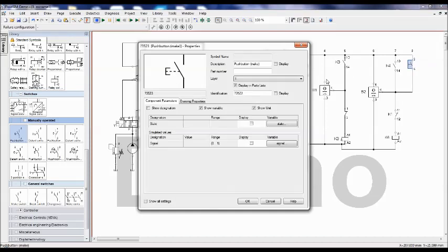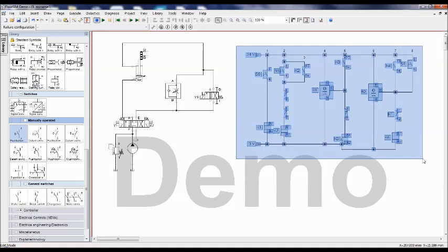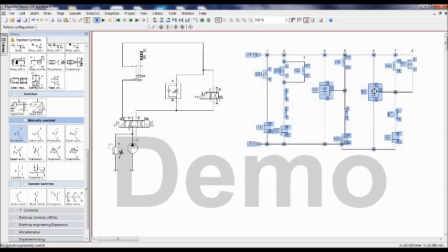In that case, the cylinder will not be able to retract at all. At that time, if you operate S7 directly, it is going to power the K4. So K4 is going to give the power to the retraction. So that is the redundancy. If the sensor is not working, then that is used.